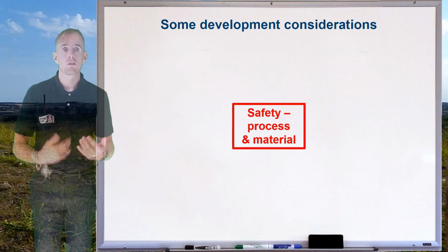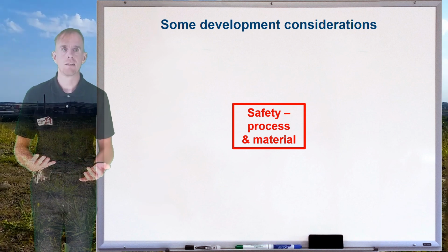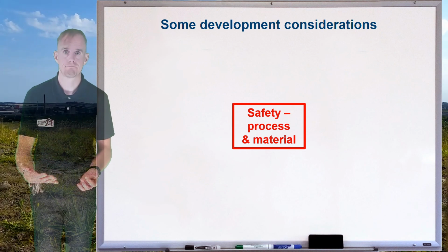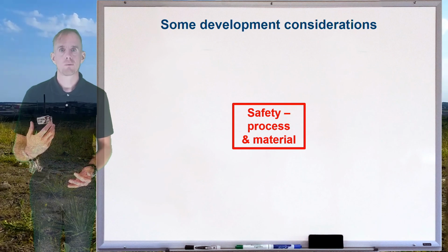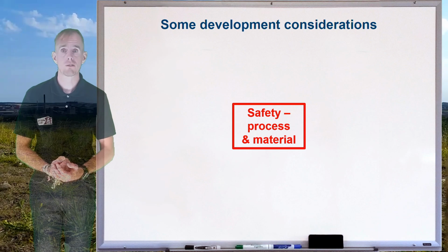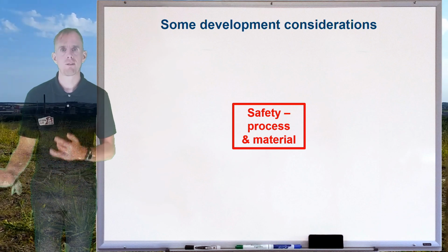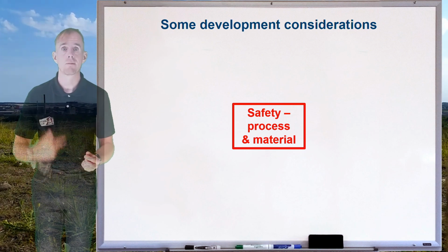Well, again, you've got to look at your catalyst and assess its toxicity. Is this a catalyst that is going to be harmful? If it is, is there something more inherently safer? In terms of what your catalyst is reacting, in this case we have methanol and carbon monoxide. Carbon monoxide is pretty hazardous. We're not introducing anything increasingly hazardous, so in effect we're maintaining the status quo by maintaining the same raw materials.